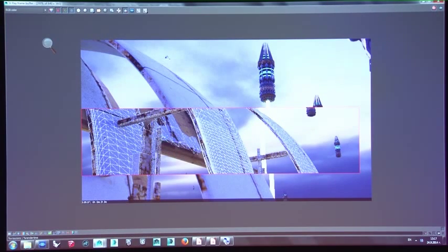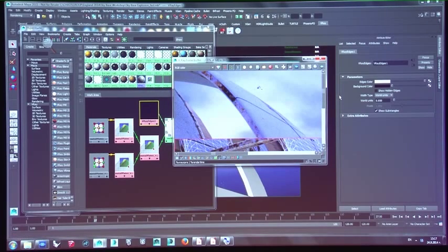let me make this larger. So you can see here we have a bit larger polygons, and here as we go further away in the distance, a bit smaller polygons, and as we go further away in the distance, these polygons become larger and larger. This is kind of a LOD, level of detail, varying the subdivision closer to the camera and away from the camera. So this is really useful, since the fewer polygons you create, the less memory and CPU power you use, and your renders are going to become faster, with the necessary amount of detail.